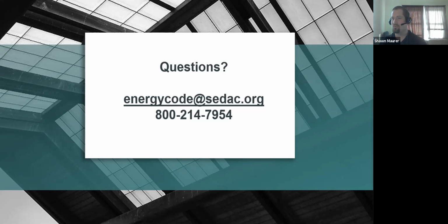Sorry about that, but we did have a few more questions come in. Joseph Zimmer put in a question and said he didn't think weather-resistant barriers such as Tyvek, Typar qualified as air barriers. And related question, is house wrap an approved air barrier? To answer those, they do qualify as air barriers, but they do have to be carefully installed.